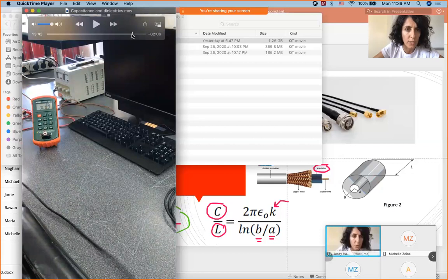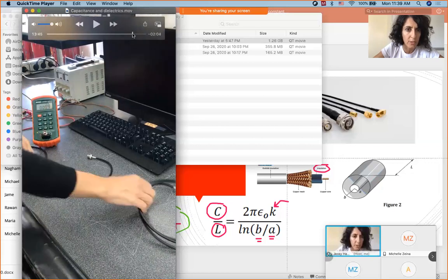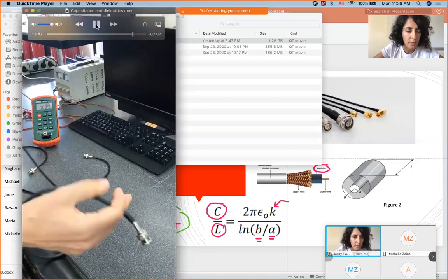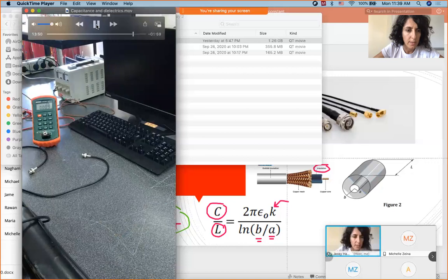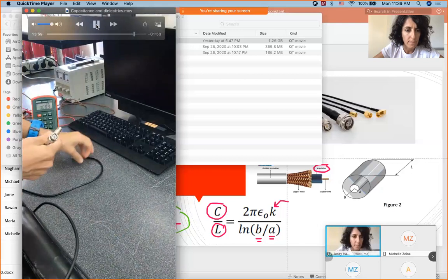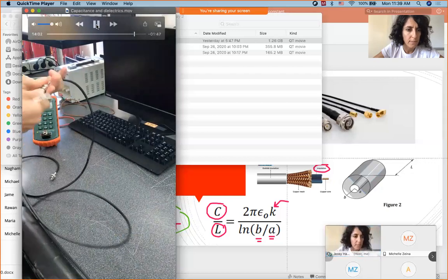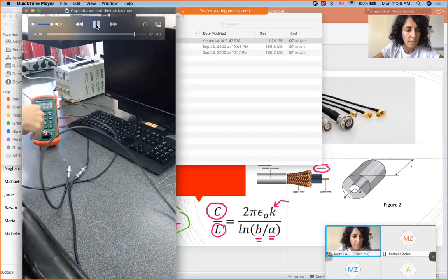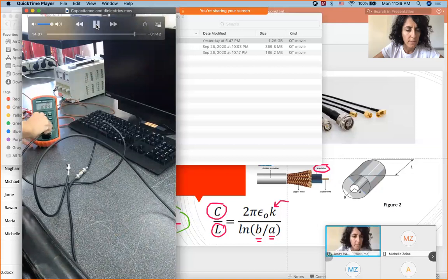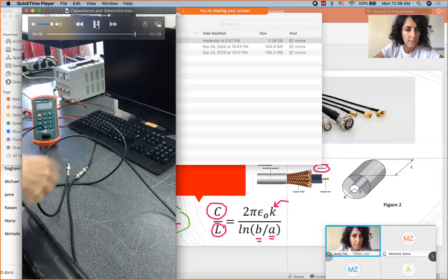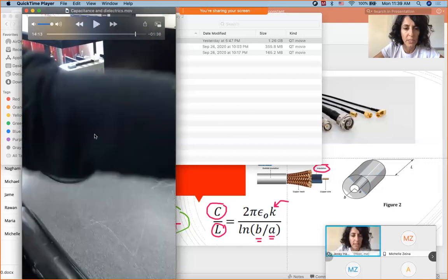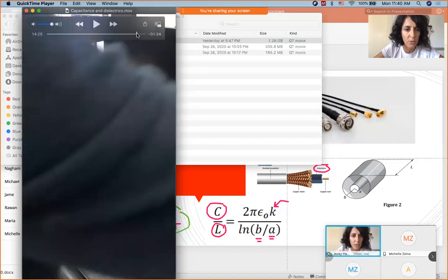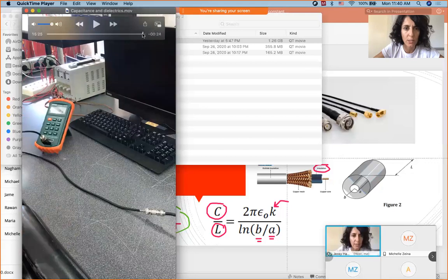All right, now let me show you the second adapter, which is a female-female connector. It's here. For cable number 2, measure the length and the capacitance. Eventually, you will be asked to connect both cables together. So this is a female-female connector. You will connect the first cable to the second cable and connect both to the adapter, like one terminal to the adapter. Maybe do this experiment on the floor to elongate. Yeah, it has to be done on the floor, because on the table I couldn't take a measurement. It has to be long and straight to be able to get a certain answer. Okay, and that's it for the experiment.